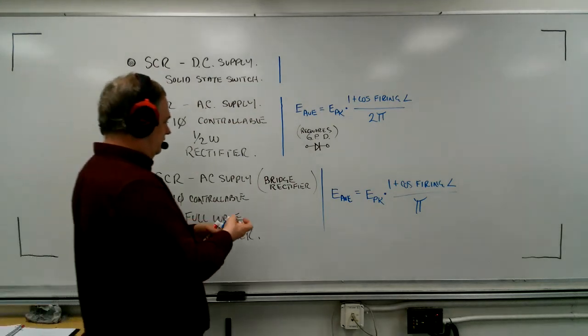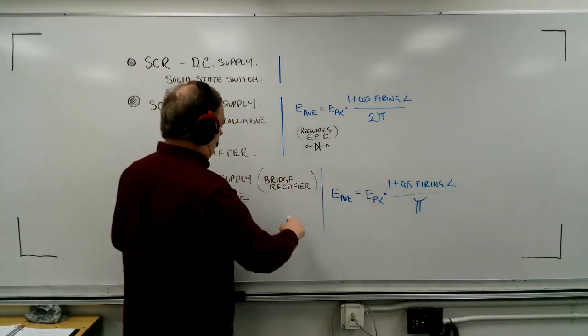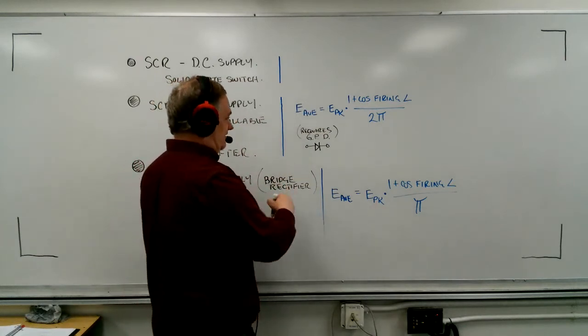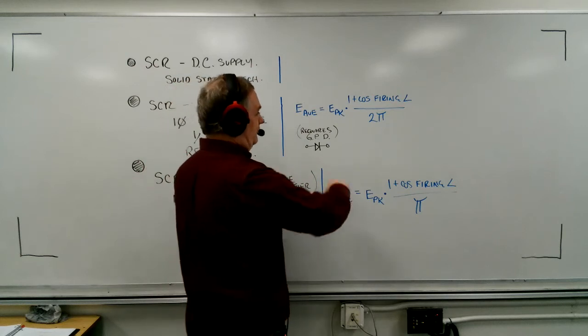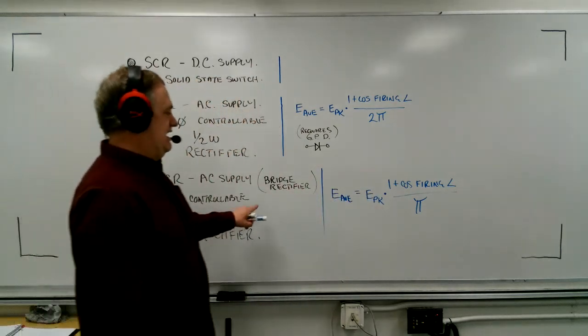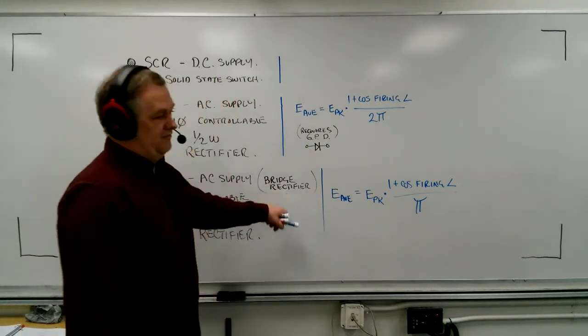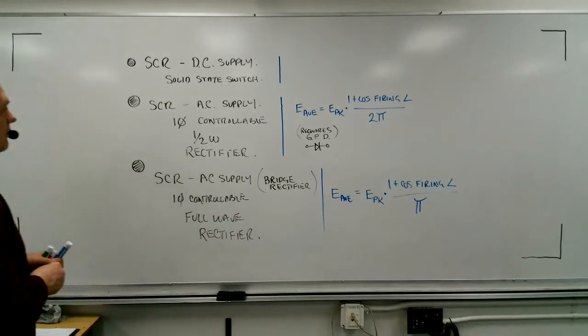And remember, with this one, because we're feeding with DC, they're just ripples. It's DC, but it's fed from ripples, all of the positive alternations. We don't actually need a gate protection diode when we already fed it from a bridge. Okay, now